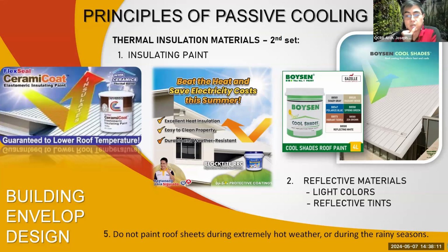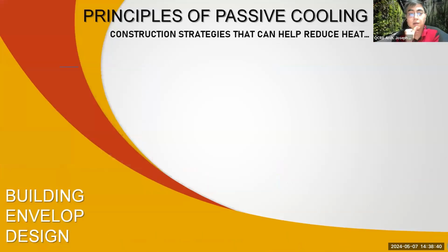Pag rainy season naman, if the temperature is humid, you normally don't paint, because the paint will contract pagka nawala yung humidity, or it will expand when there's humidity, so it will not cling. At the same time, if it rains within how many hours after painting, it will just wash off your insulating paint. It's a waste. Follow instructions from the painting company. So ideally, when you contact your painting company, you ask for referral for their accredited painters.